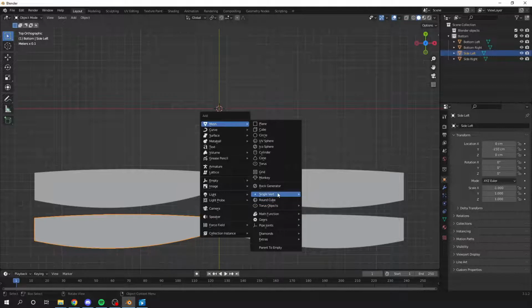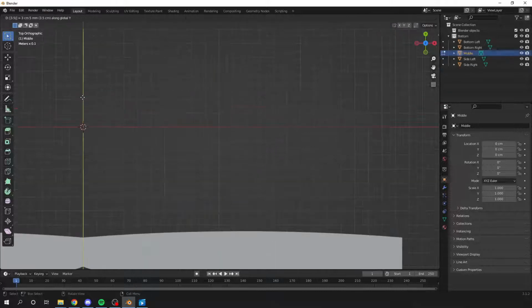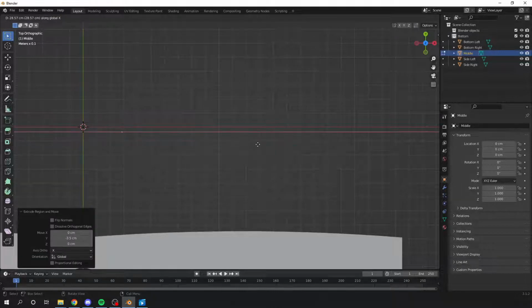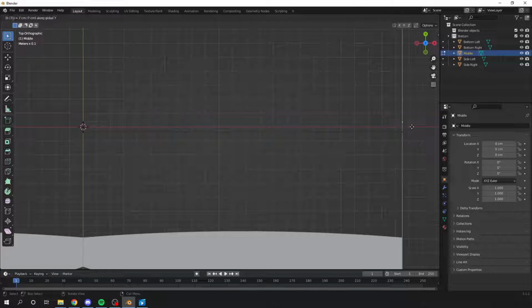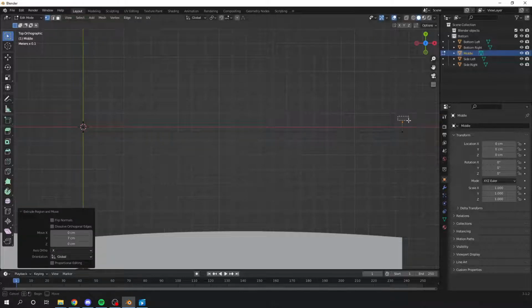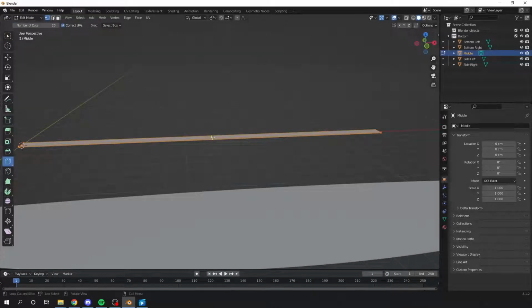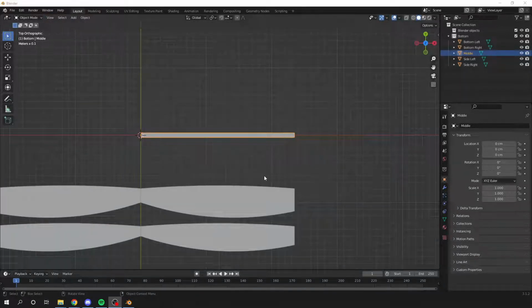The middle panel is a very easy part to create. It's just a square that is 7 centimeters wide and 2 meters and 35 centimeters long. So to create the new vertices, I just press E to extrude the vertices and then press X or Y to limit myself in what direction to extrude, and then press in the number for the length to extrude. To create an edge between two existing vertices, you just use F. This is the same command as if you select more than 2, and then it will create a face instead.